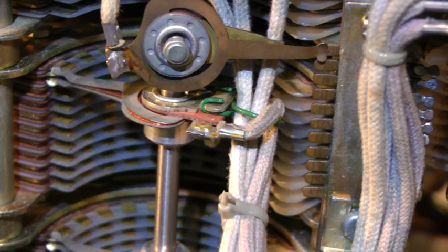However, now the commutator wiper is resting on the 10th commutator segment, which corresponds to the level on which our line circuit, terminal 00, is located on the bank assembly. This commutator segment is grounded. It actually has a permanent ground on it since it is at the highest level and acts as a failsafe to prevent further attempts at vertical stepping.